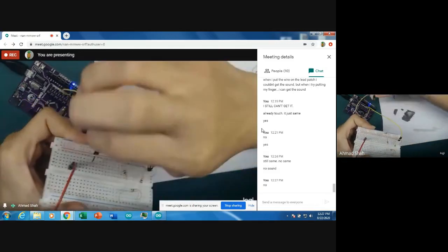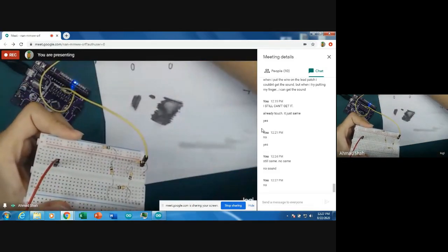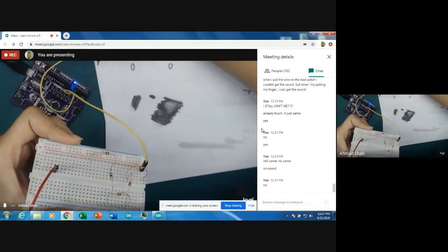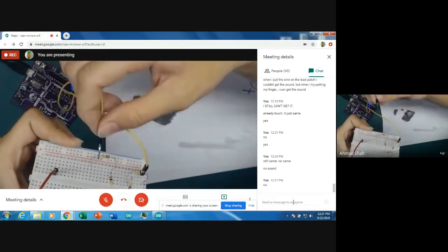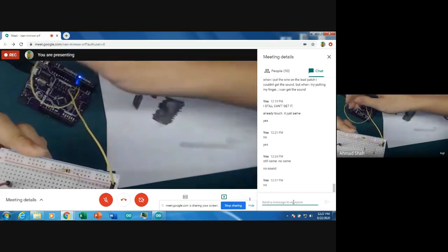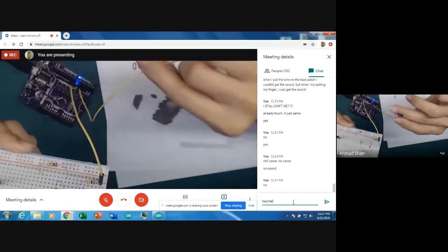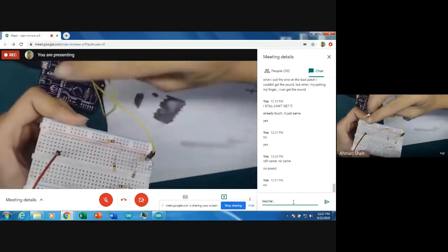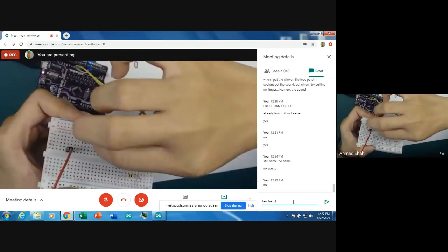If you did not, it will show -2. So check again if your pin is connected properly or not. The wire that is connected to pin 6 is connecting to the last resistor.